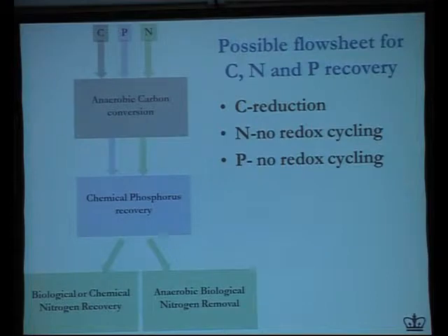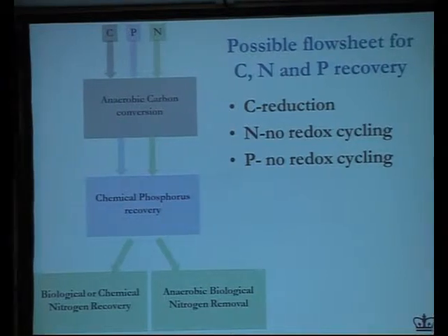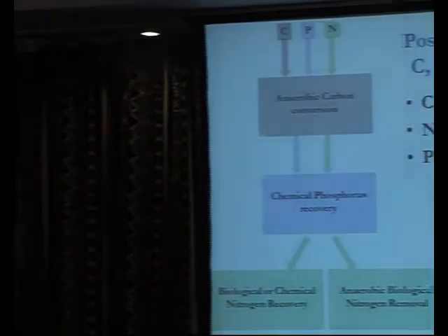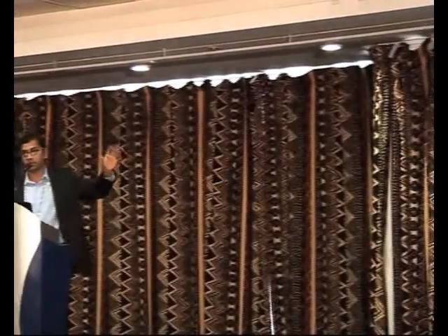So this is not a random order. What I propose here is a specific hierarchy of steps, or rather sequence of steps, whereby we address specifically in a targeted fashion carbon, phosphorus next, and then nitrogen, and primarily oriented on anaerobic processes and also primarily oriented towards recovery. And a lot of this, we don't have to invent new processes. This is not Star Trek. This is something that we know how to do. It is just reorienting the processes to an endpoint.